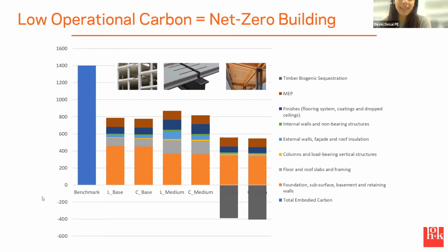So that's really, really big low-hanging fruit, if you can find some way to reduce the quantities of the material you're using on the foundation. Maybe there's some existing foundation elements in the field that you can make use of. Maybe you can put as much fly ash in the foundation concrete as possible to reduce your reliance on cement. All of those things will reduce your carbon emissions associated with the foundation, because again, what we can't see, it's underground, it's actually the biggest piece of the pie. And below the gray line, yes, thanks for mentioning. That's a good segue into what is this negative carbon here.